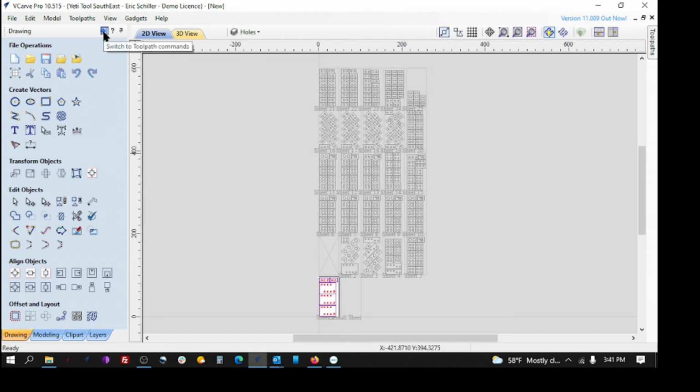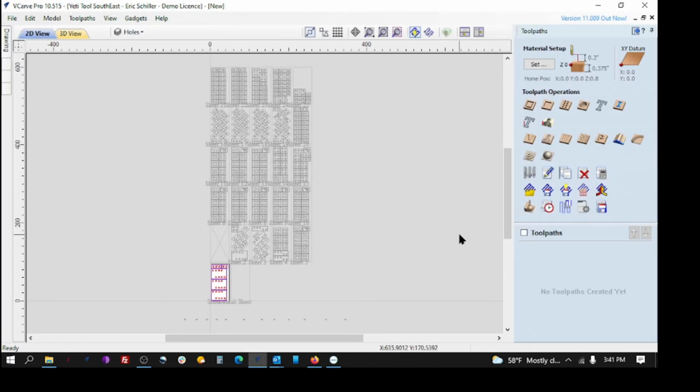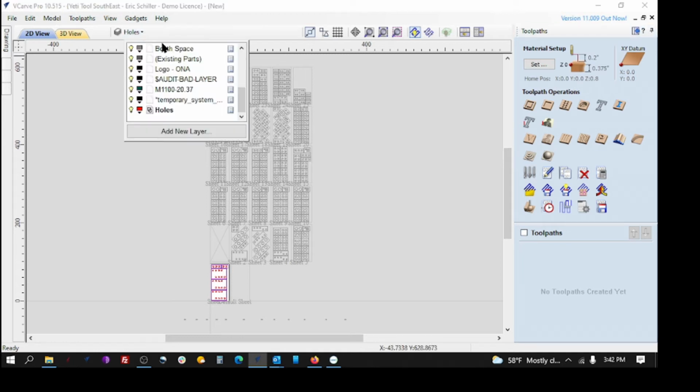And so we're going to switch over to this, and we're going to set the tool paths up. What happened is when this came in with the DWG, these are the different layers that came in. And really all we care about is the borders. So I'm going to turn off the text and the dimensions and the centers and viewports. Again, I don't need any of this. The parts that are going to be interesting to us would just be the holes and the border.